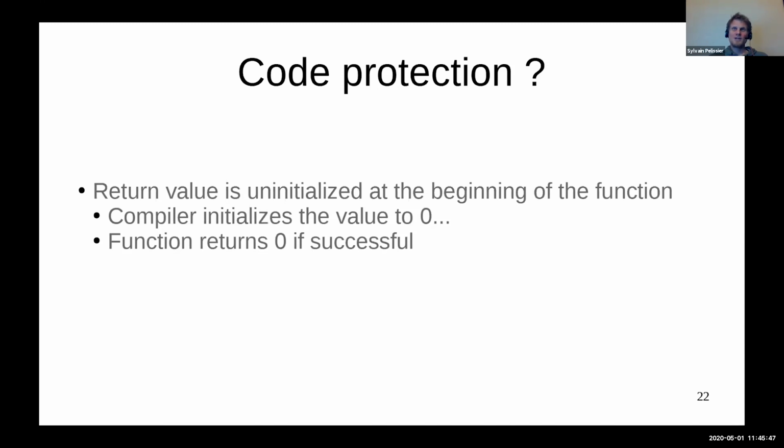And it was really nice for us, because when you do a fault attack, sometimes you skip a large part of code, you are not that precise. But if you have a function which returns the uninitialized state and which will be seen as successful, it's really nice, because then you don't need to worry about error detection. So that was something which helped the fault attack a bit.